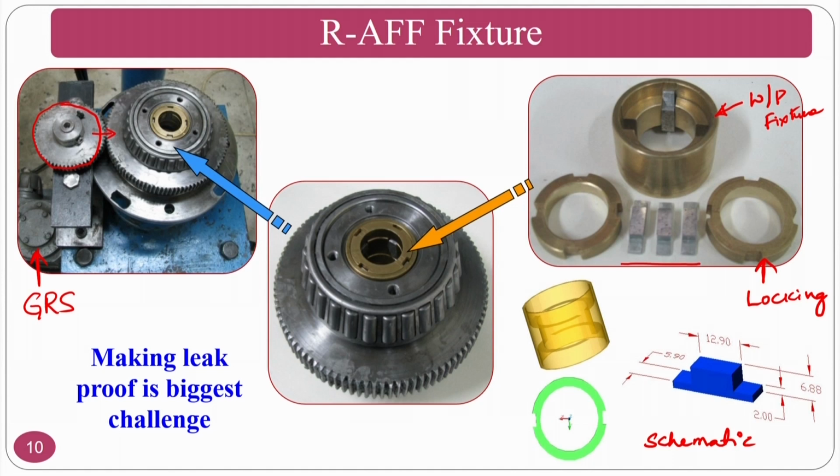Normally you have 4 slots, and you can provide 6 slots, depending on your requirement. As per this particular design, we have 4 slots. The 4 slots are held by the 4 slotted locking plates and other things, and you can see the dimensions of your workpiece in the schematic diagram.